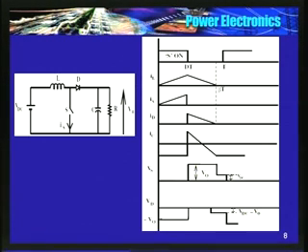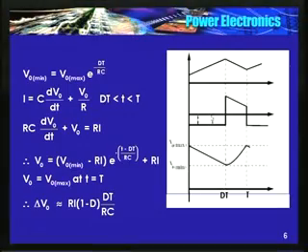So if you see a continuous conduction period, the capacitor is charging for the entire off period of the switch. At this point, just prior to closing the switch, inductor current is higher than the load current.